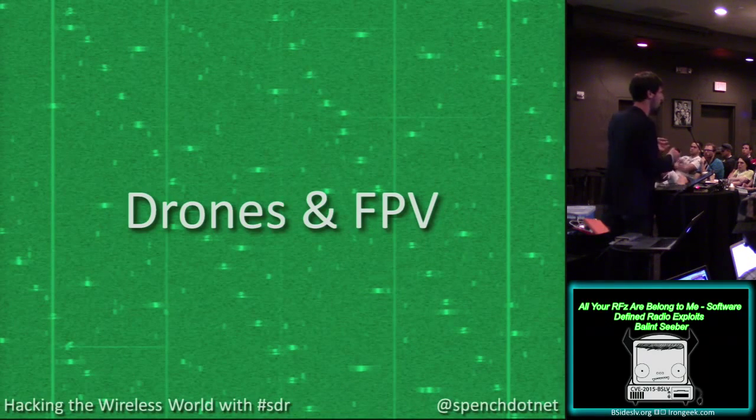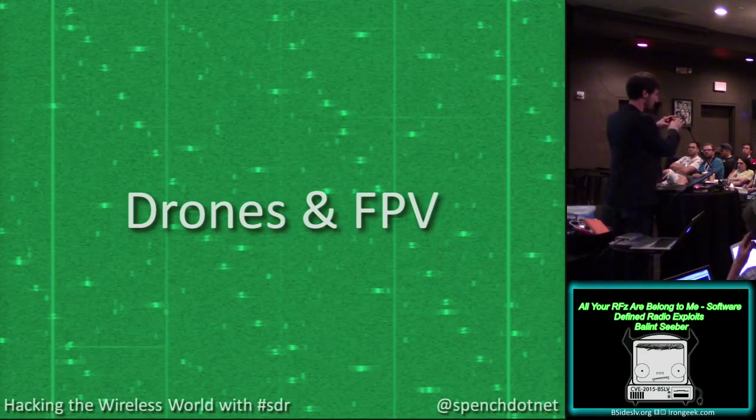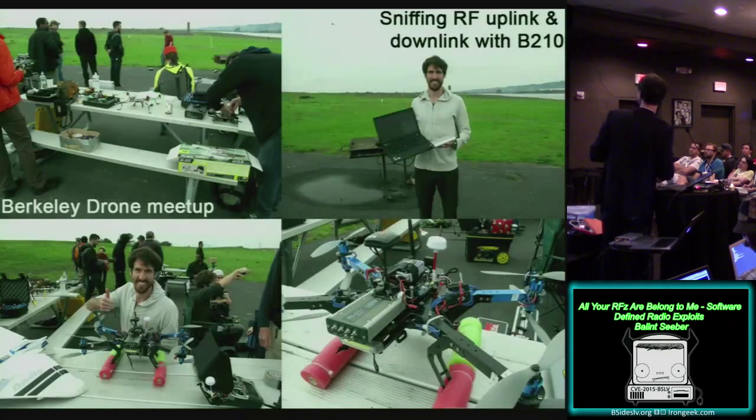And these remote controls use frequency hopping, so you can see that you end up having these little packets that aren't transmitted on the same frequency all the time, but they hop through the spectrum. And this allows for lots of people to be using this same band at the same time. So it means that you don't have to individually allocate a particular frequency to a person. They can all hop through this region, and if all goes to plan, they won't interfere with one another. So it's a really effective way of sharing the radio spectrum between multiple users. So I went out there and used a B210 there to capture that radio spectrum.